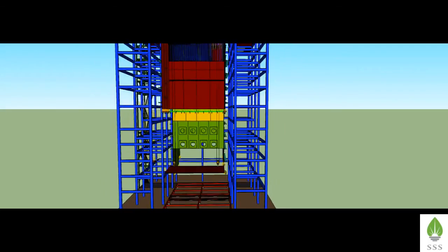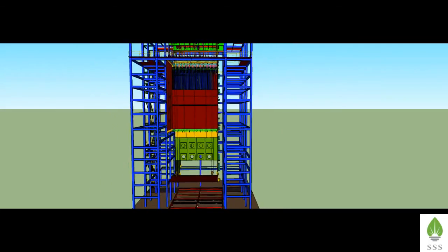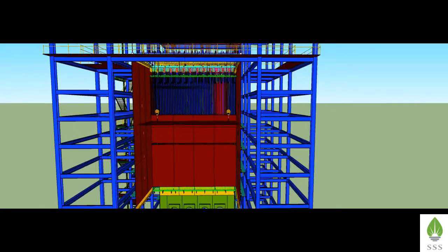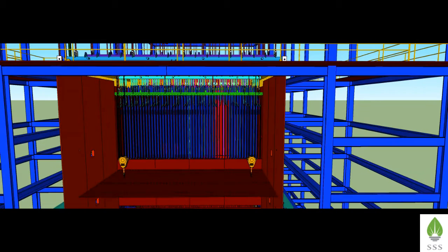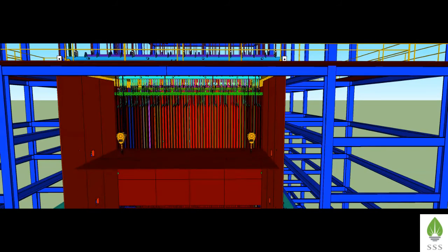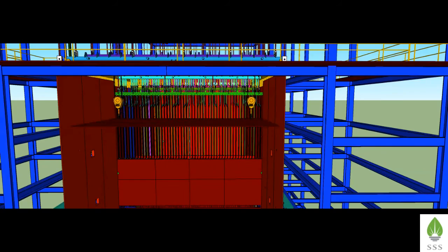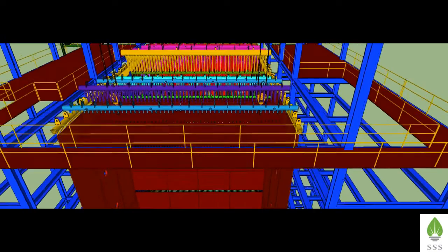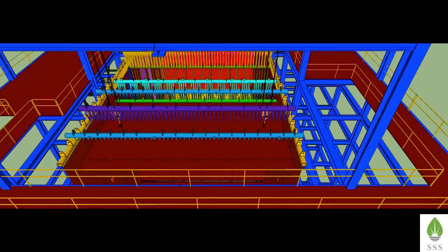Roof panel contains openings for the economiser stinger tubes, primary superheater coil and reheater loop tube. Weld one end of the roof panel with the stub of roof intermediate header.